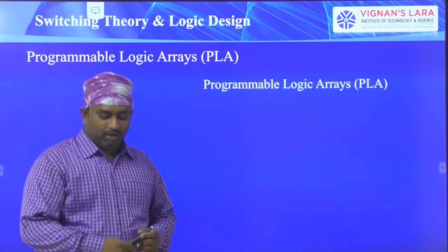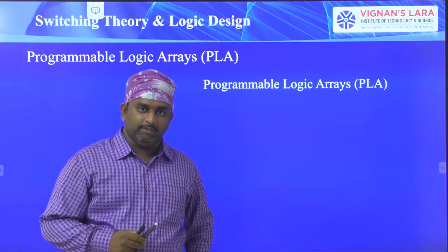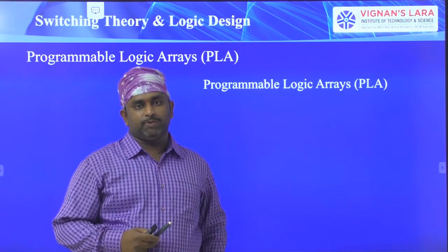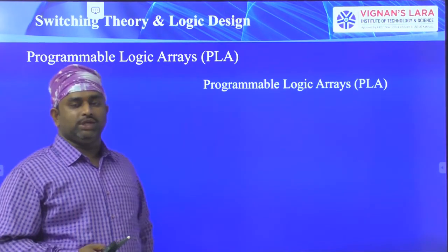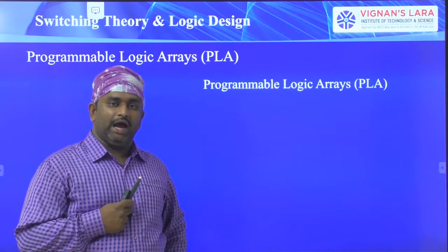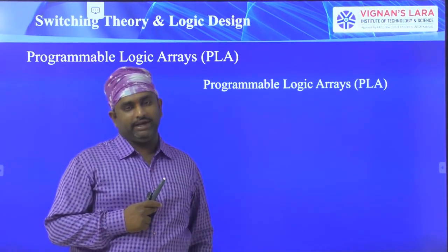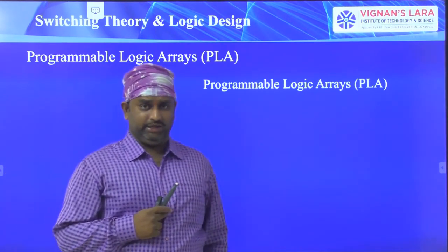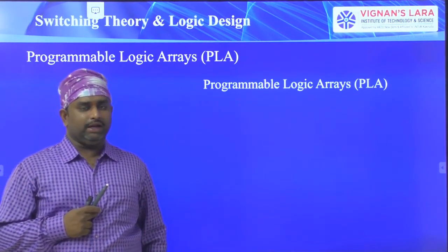See here, in the previous class we discussed programmable read-only memory, where the PROM is the memory device, and after that we discussed the programmable array logic, which has the freedom of connecting the AND gates based on the user's choice, that is, programmable AND gates are available, and industry-specified OR gates, that is, fixed OR gate arrays are available in the programmable array logic.